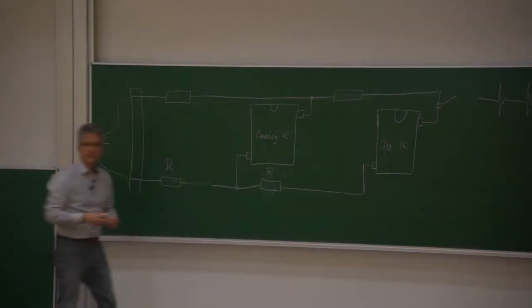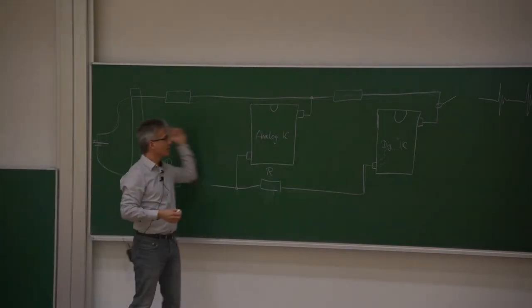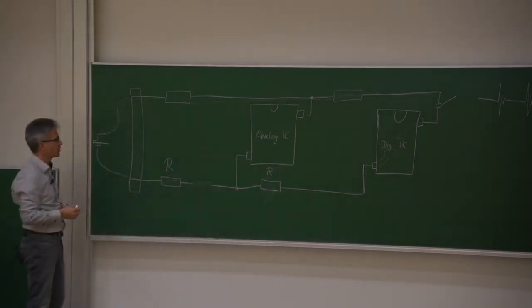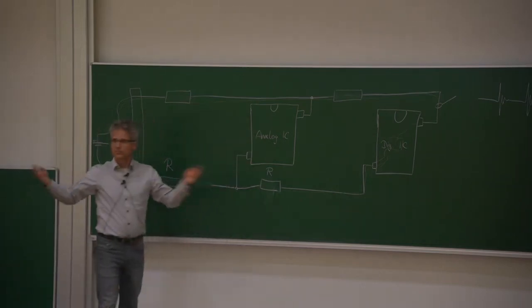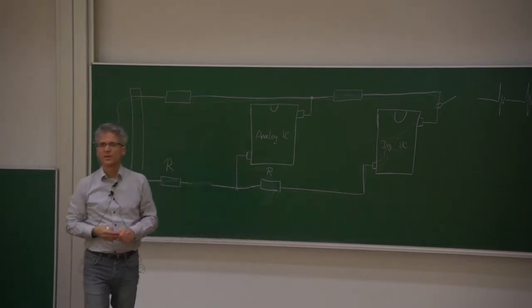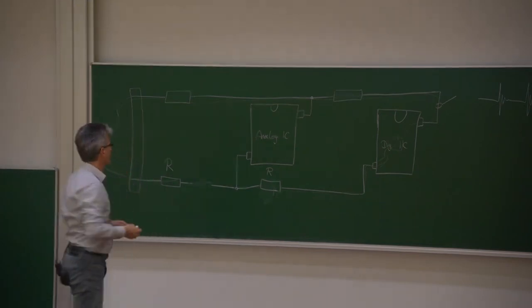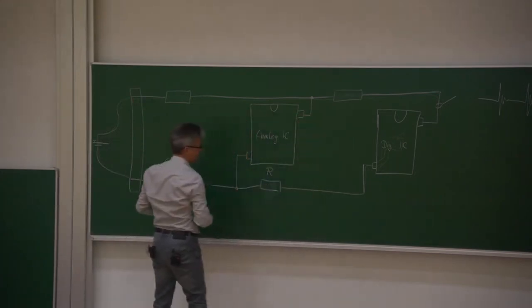But, as was also mentioned today, there is also a parasitic inductance, because the current is flowing in a loop and our loop is pretty big. Unfortunately, it's pretty big. So the whole loop area is forming an inductance. And we can split the inductance into several branches. So we can give this branch here an inductance, this an inductance, this an inductance, this an inductance.